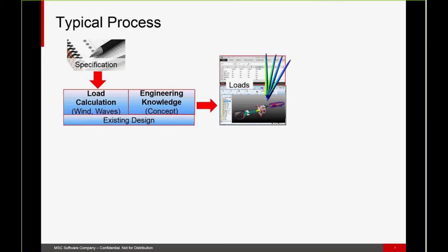You need the loads for the components. Components are things like the blades, the main shaft, the main frame, gears, bearings, whatever you are using in your wind turbine application. The loads are needed for these components to give a rough estimation of what the behavior and the lifetime will be. In many cases, you are using the DIN or ISO lifetime calculation. This means you have a component, an analytical description of your component, and the loads, and you get a statement with respect to your lifetime.